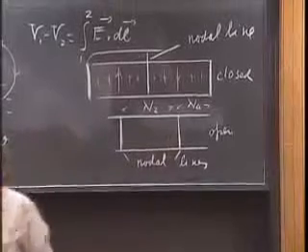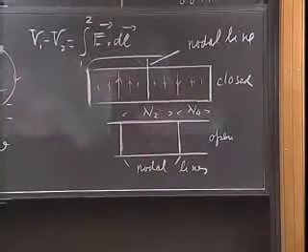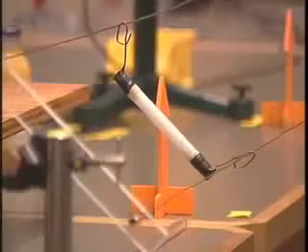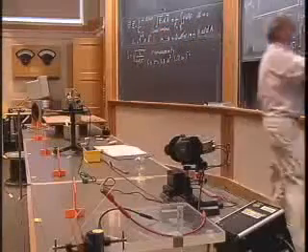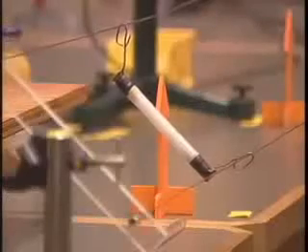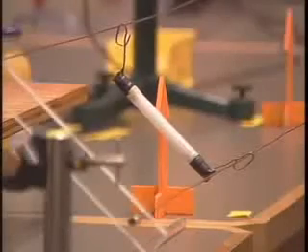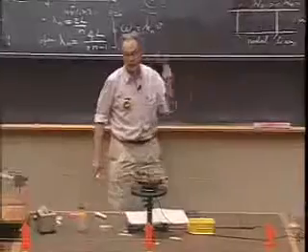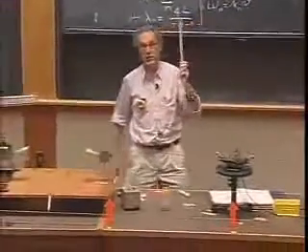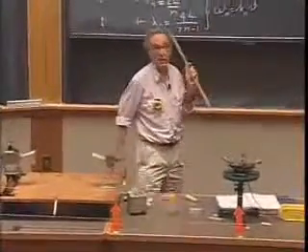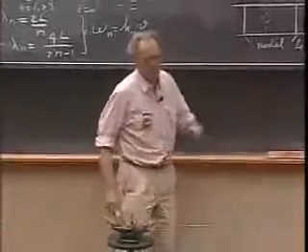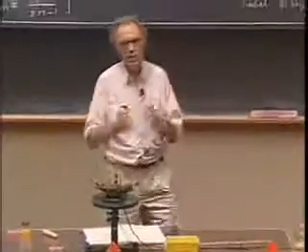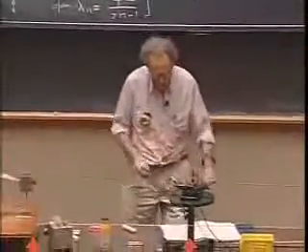If I leave this open, and that's what I'm going to do, I have here a light connected between these two wires that I can slide along, a light source. This is a very special light source, it has an enormously high ohmic resistance, so that when I put it here, I'm not disturbing the potential difference between the wires. I'm not changing the boundary conditions, really, because it has an enormously high ohmic resistance, and that light bulb lights up even with a minutely small current.